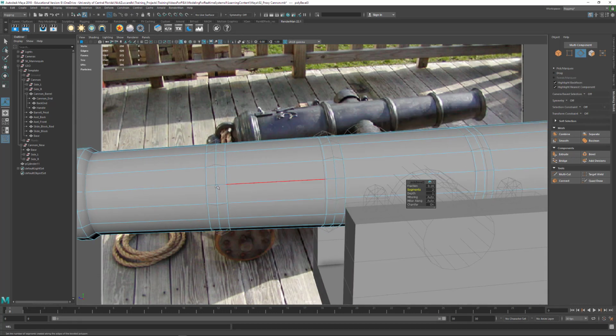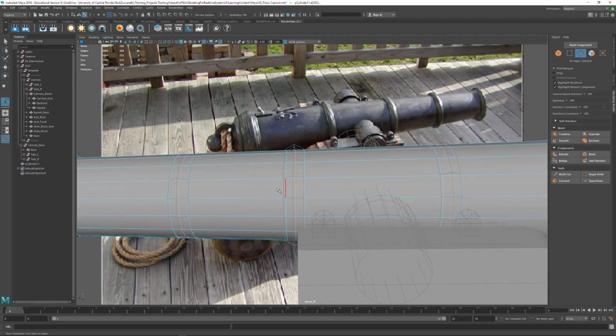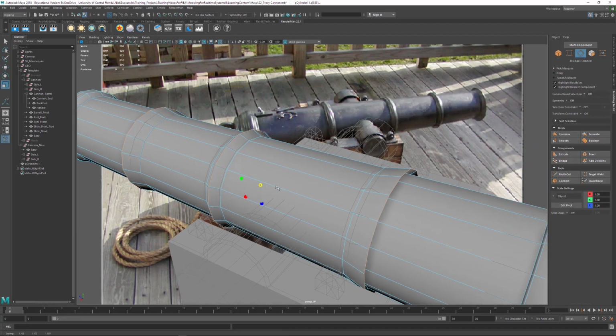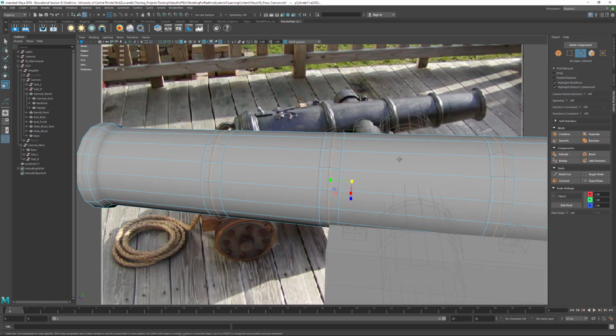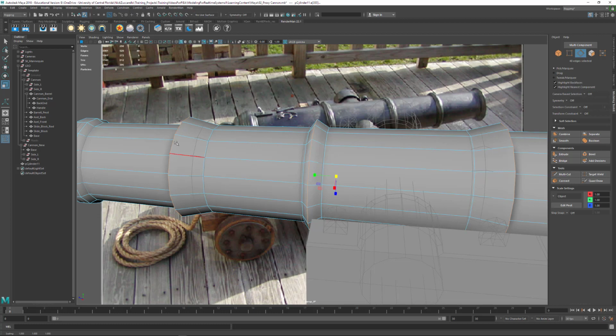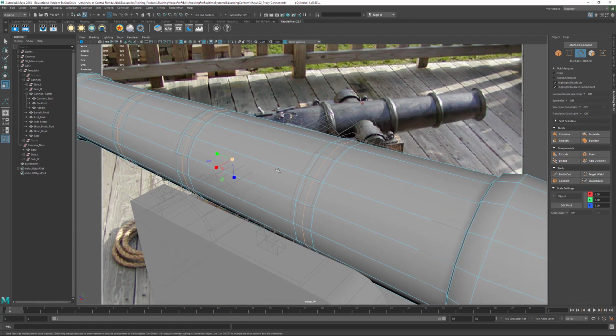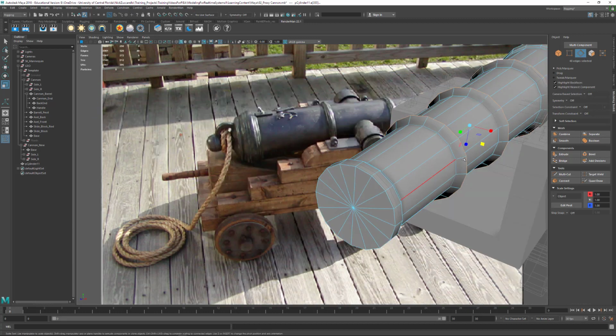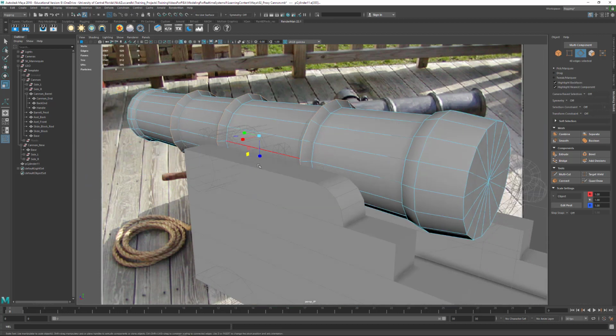They're all the same size, and we've got these edge loops that we can select this, hold down Shift, select this one, and select this one like that. And then now we can scale this thing out. Now I was going to show you if I do this uniform scale, we can do that, but you can see what's going to happen here. It's going to scale this thing out this direction, this one's okay. Now if we just scale in these 2 dimensions like this, we can just scale out and it won't scale anywhere along the Z. So we used this little cube thing to kind of scale that thing out like that.